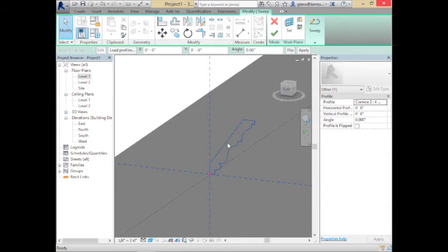Now you can see it's a little high right now. It's going to fly above the wall as opposed to being in the wall. So I might want to put a little offset to it. We've chosen a path but it's not quite right, I can put a little vertical offset or horizontal offset, either have it stand off the wall or drop it down. So let me just drop it like 5 inches and see if that works. Might have been a little bit much, maybe -4 inches.